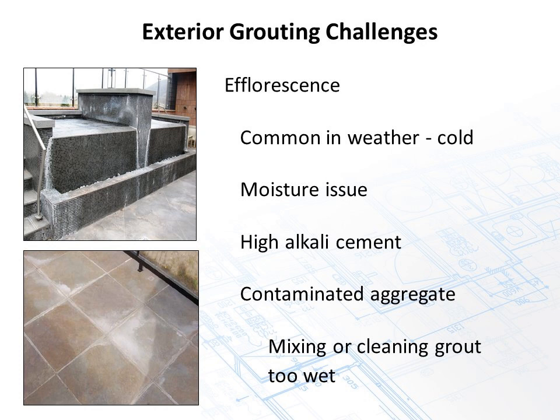The upper picture you see is a hot tub in Aspen at a hotel. Pretty efflorescent, I will say. So generally, efflorescence comes from a moisture issue. It's water-soluble alkali, so if moisture is present or if there's excessive moisture there, when it does evaporate away, you'll generally see this mineral or salty type material left behind.